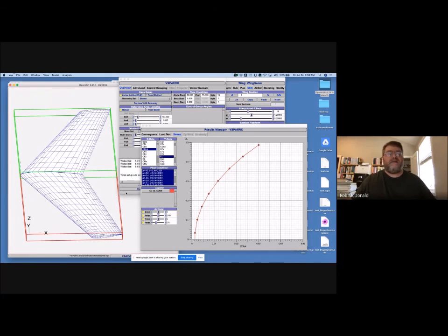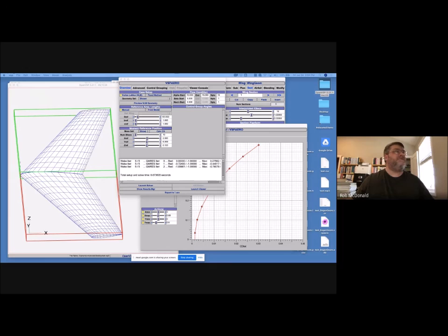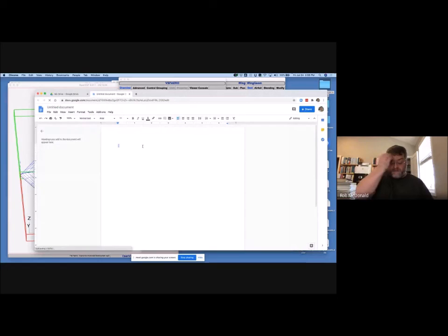Let me do something super quick here. All I'm doing is writing something. I just said your weight is 35 pounds, and let's say your reference area, your wing area, is 10 feet squared. So your wing loading, which is W over S, is going to be 3.5, and that's pounds per foot squared, or sometimes we call that PSF, pounds per square foot.